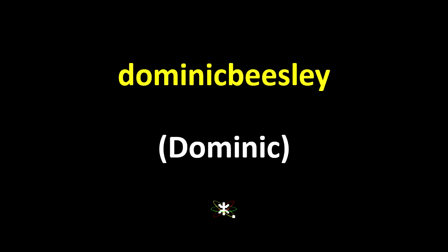Cool. And then another one. Do you know anything about when you're doing FPGAs and CPLDs, if you keep the slew rate down, do they tend to not work if you just do a two-sided board, or do you really need a 4-layer board? You can do CPLDs and FPGAs on 2-layer boards, but the real thing is to try and keep the signal integrity up.